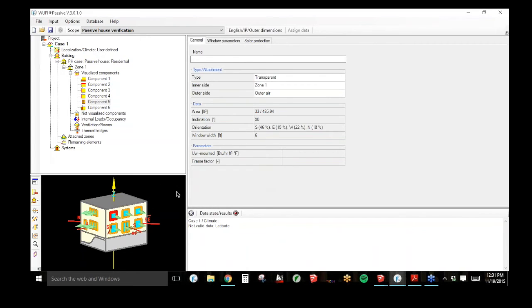It might be walls. So I'm just going to quickly look. It shows me the window width is 6 feet. That looks about right. And so it's about 5 feet in height. So that's about right. You want to make sure you're not off by a scale of 10 or something, or maybe you're using metric in SketchUp.